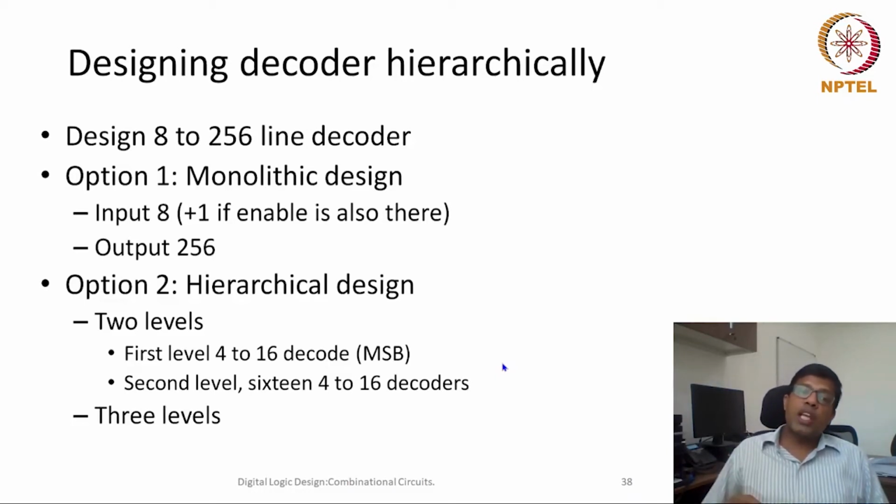Now, if I want to design a 9 input AND gate, eventually that AND gate has to be again designed using multiple AND gates. So that would increase the cost. Otherwise, if I am using a monolithic design of one 9 input AND gate, then the delay would be much more. So that is why it could be a better idea to go for a hierarchical design from the first place itself.